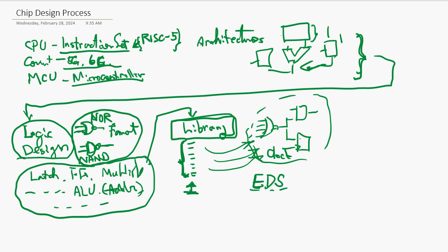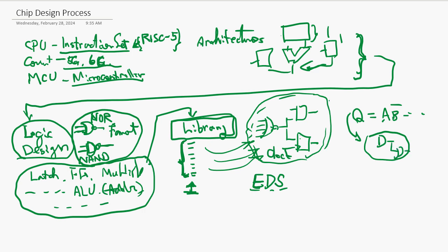You pull out the library and put it together and make the logic diagram, the entire diagram of the chip. Okay, and of course, if you like, your preference, you can use a logic equation like Q equals A, B over whatever, and the program converts it into the optimized logic diagram. And this is a very important tool for random logic, like the instruction decoder and stuff.